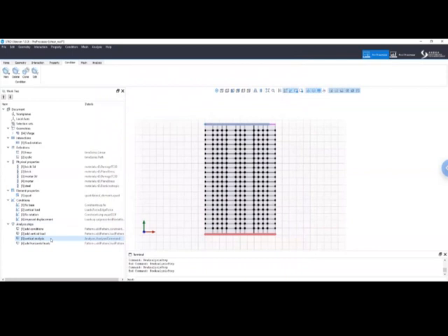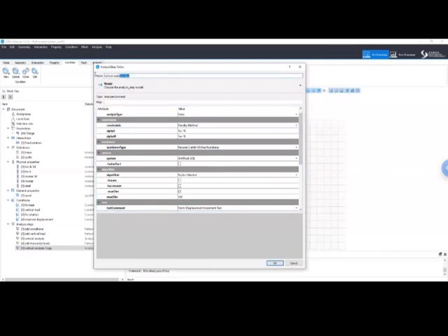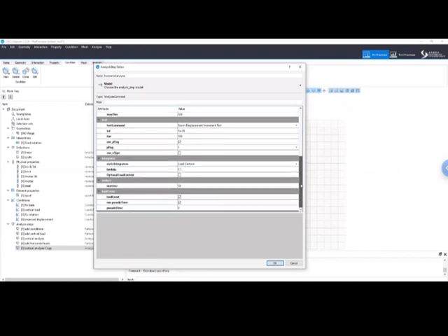Now the settings will be very similar to this one. So instead of creating a new one, we can just right-click on the previous analysis and click Clone. And now we're going to edit just the small differences. So everything is fine like this. Let me just change the name from vertical analysis to horizontal analysis. And then let me do just a change here.